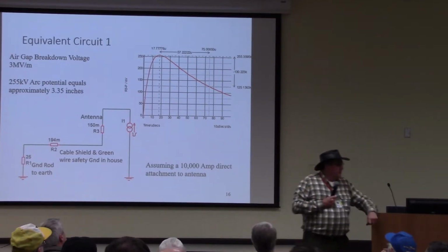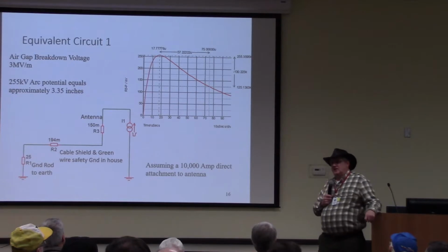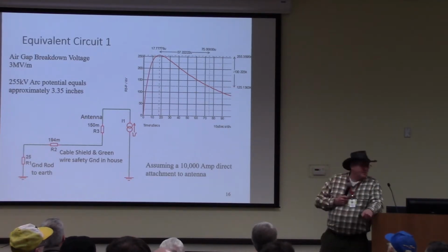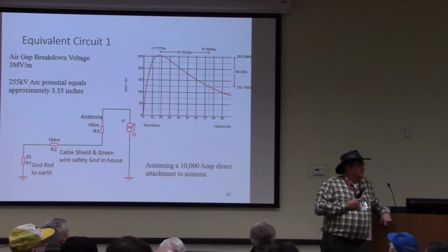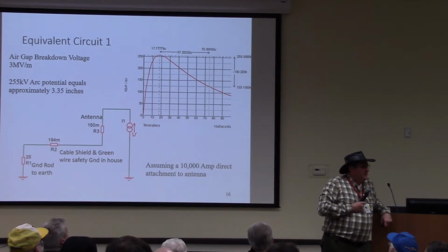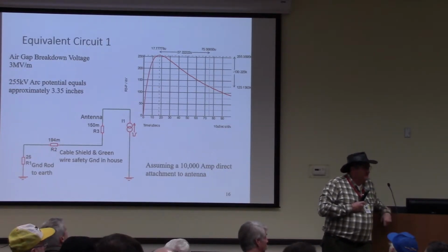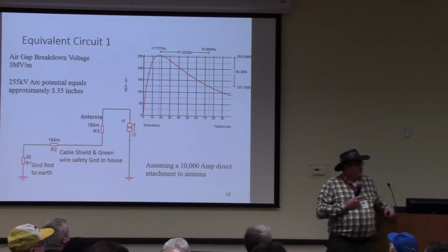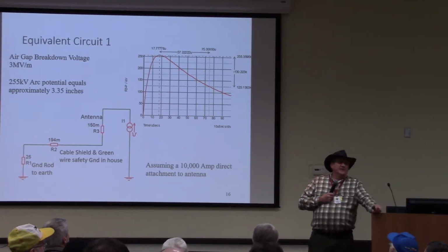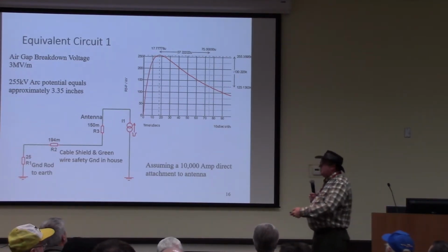And you notice that it's 25 ohms. Where did I get that? Close enough, because it is a very low frequency that they use when they take the measurement in the ground potential drop-off test. So I'm using the 25 ohms.